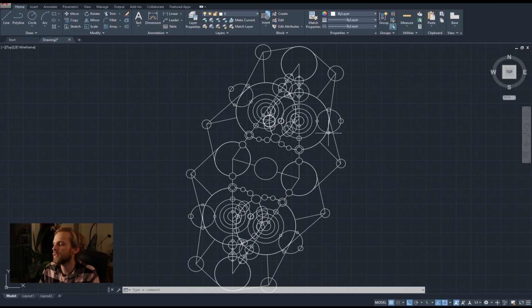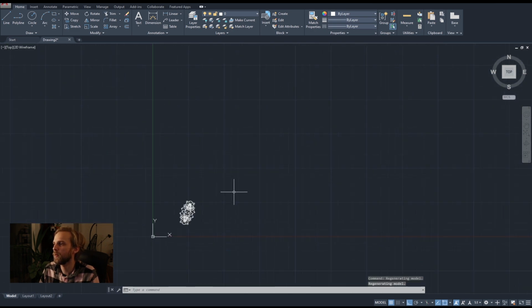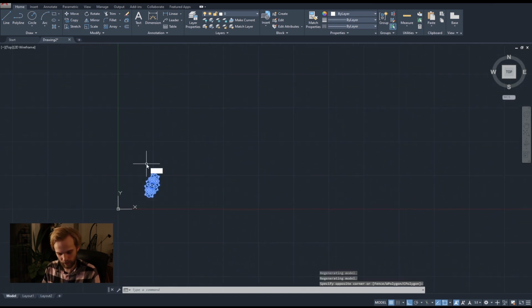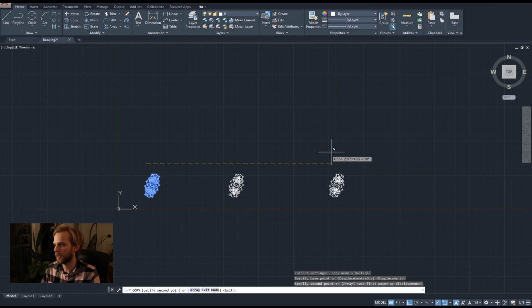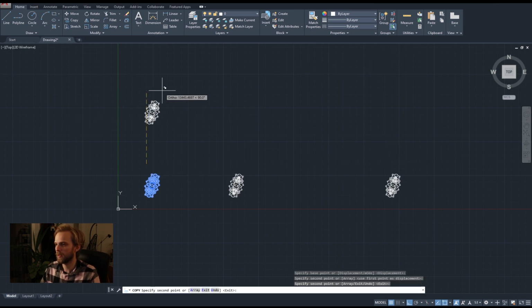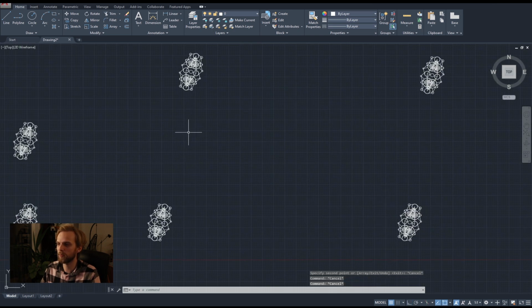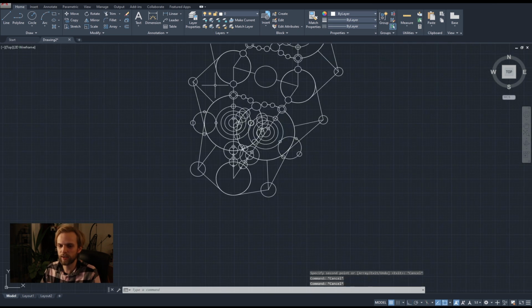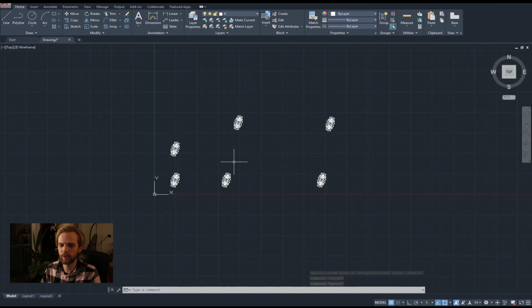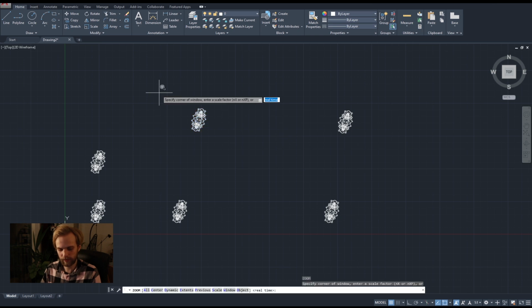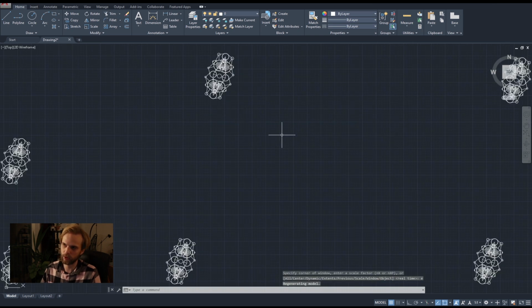But also it's quite useful when you have multiple drawings on one sheet. Let's say you have multiple drawings on one sheet, and just so that you don't need to zoom in, zoom out, what you can do is select the object, then Z, enter, E, enter. Oh, sorry.